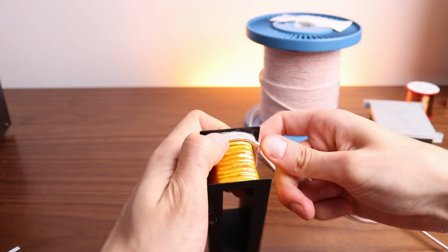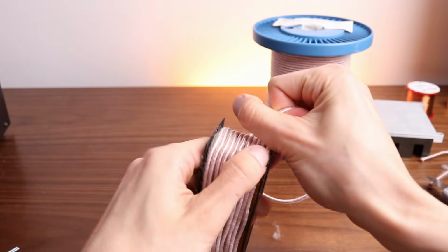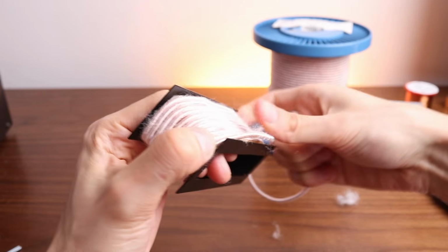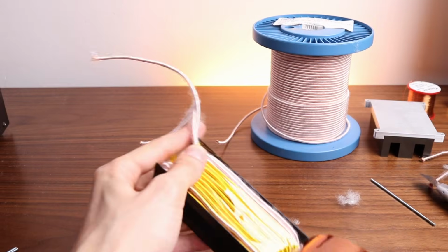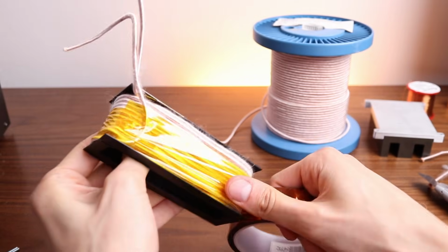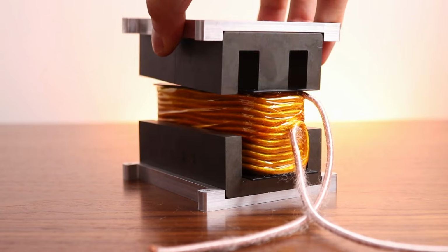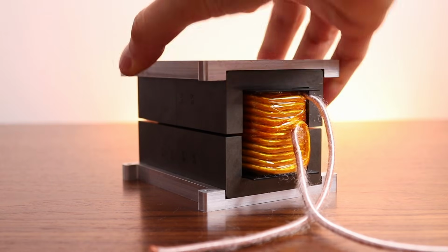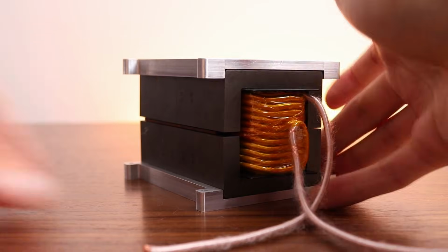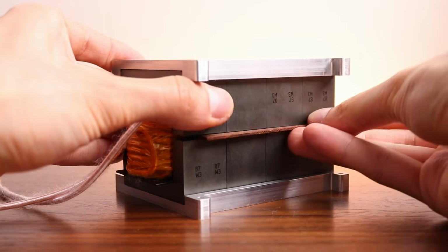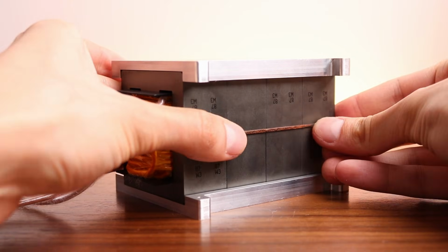During the winding process, I try to keep the wire under tension, so the winds lay down close to each other and close to the plastic. Eventually, at the end, I managed to fit one more turn on the first layer, ending up with 23 turns instead of 22. That should theoretically increase my inductance to around 490 microhenries.